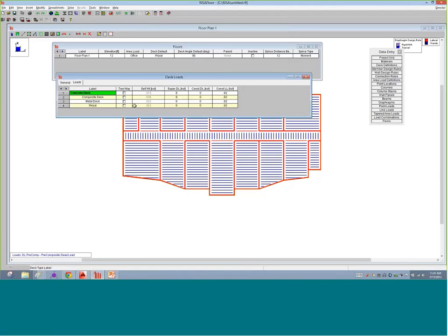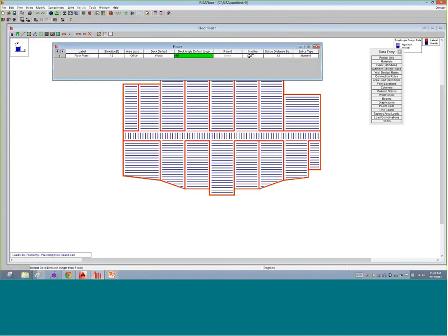The loads, I can tell the program here, it's calculating its self-weight for me. If I have any superimposed dead loads, so any loads that are going to be above and beyond that dead load, I can put that there for more of its deck materials. Maybe there's sheathing that is attached to that deck and I want it to be above and beyond what I have as self-weight. Any construction or dead and live loads I can put in here. So I've got that all listed as my wood deck default.